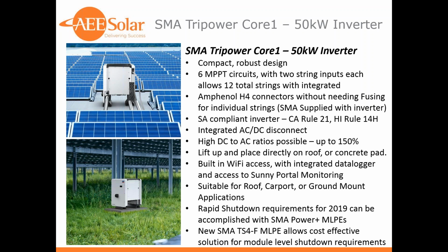These have integrated Wi-Fi access, easily configured using a smartphone or a tablet. And we've had people install, for example, ingenious long-range wireless bridges that would create a Wi-Fi network up on the roof that all these easily connect to. So we don't have to run the data wiring monitoring from inverter to inverter to inverter, daisy chain style, making integration and monitoring these very easy.